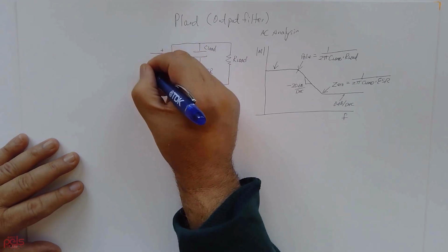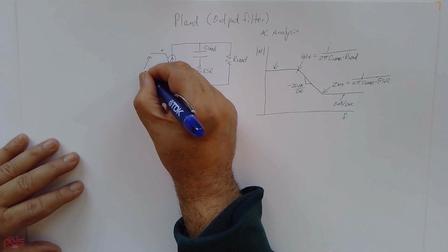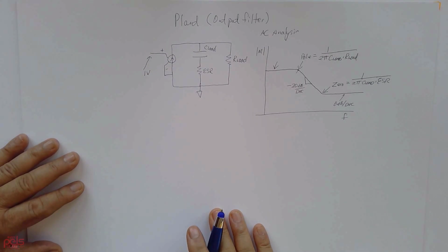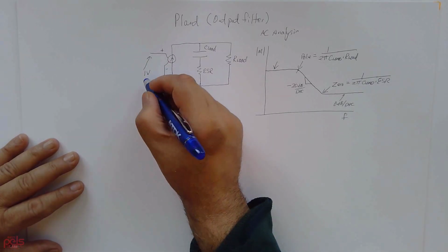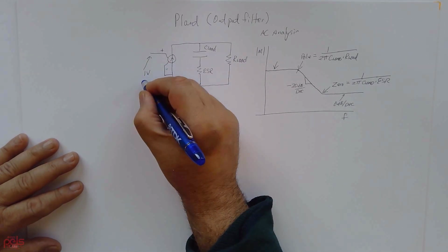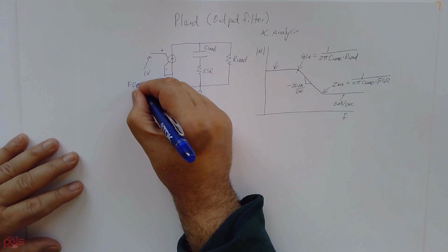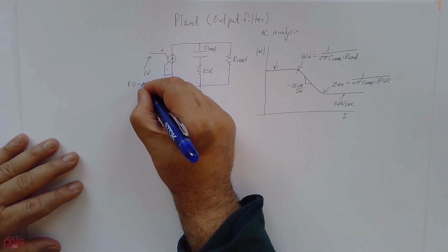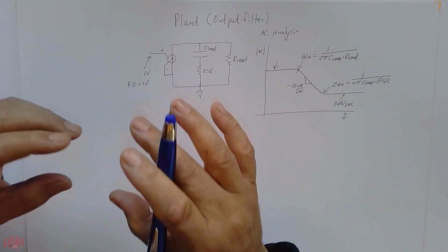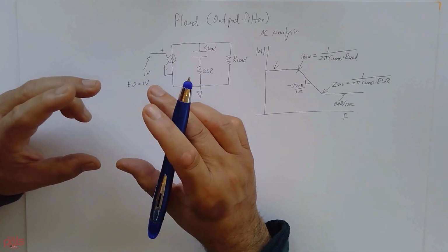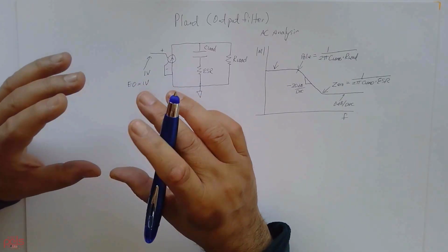Typically, you want to set the input to 1 volt, because for your error amp, you want the output to be about 1 volt, since inside the PWM there's a comparator and there's a 1 volt zener. So you're restricted to that range.